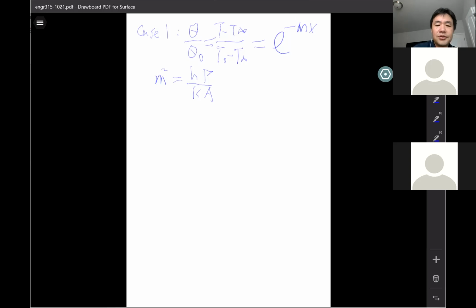And the Q, the total Q loss, is important to know. The total heat lost through the side of the fin to the surroundings is how much heat you can transfer. That's the goal, the industry application of the fin: we want to transfer heat from the base to the surroundings, and the more heat transferred, the better.